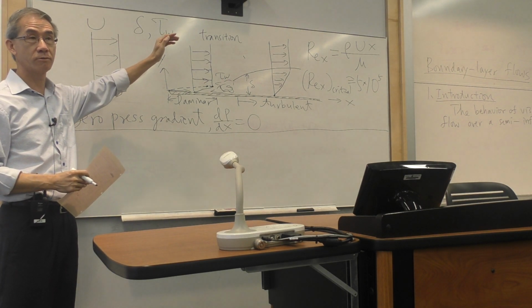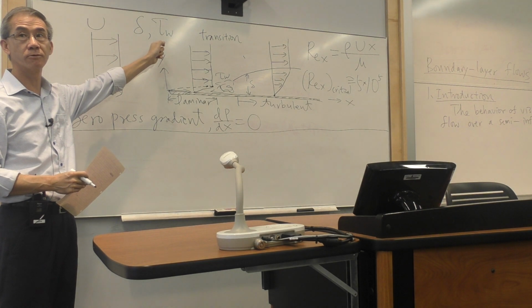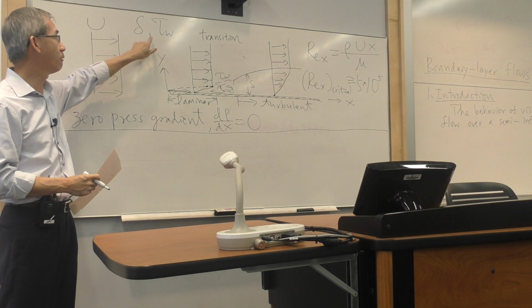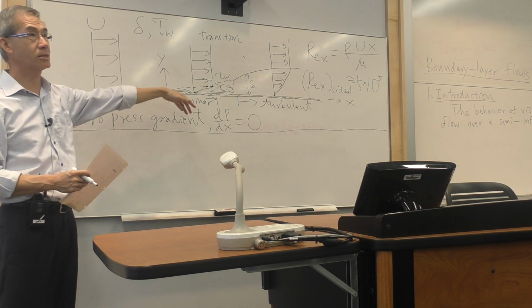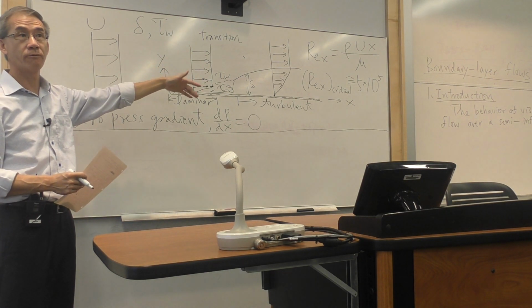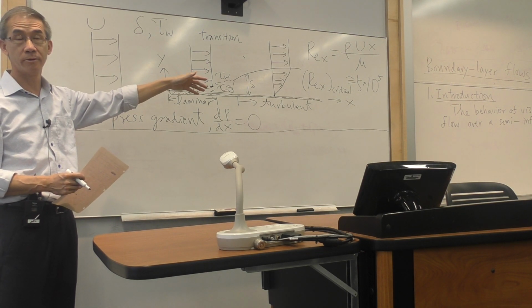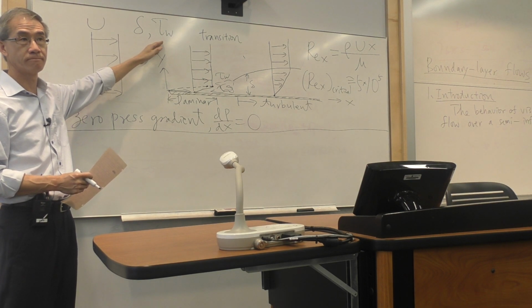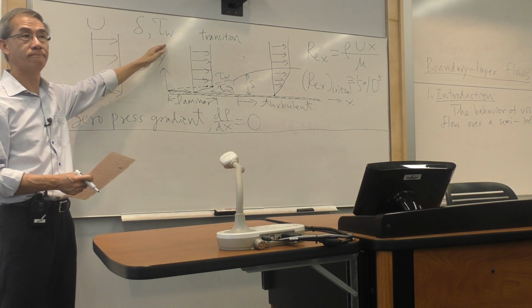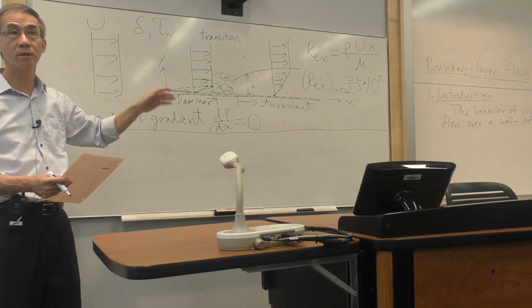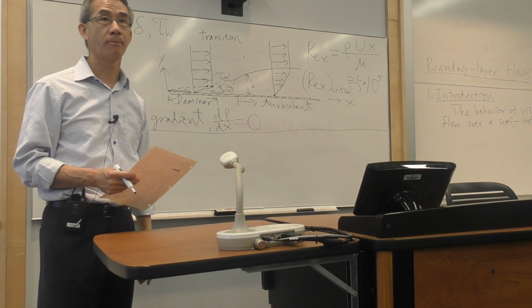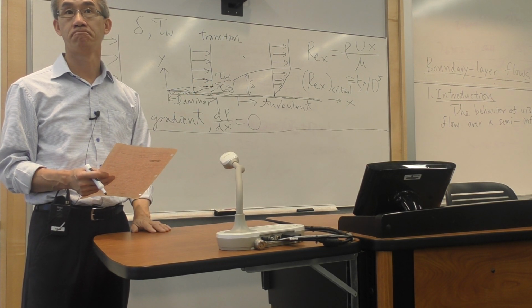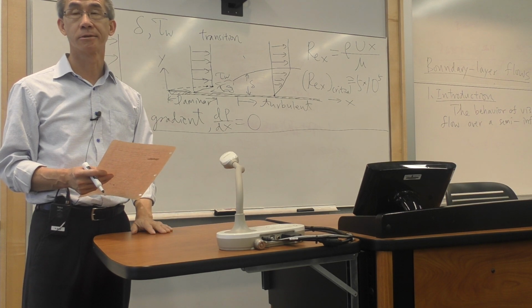And actually in 2 or 3 weeks, I'm going to derive those equations for you so that I have a tool to estimate how thick the boundary layer is at a distance of, say, a foot from the leading edge of your car hood. And I'm going to also estimate at that location what the shear is. Is it 10 pounds or is it 100 pounds? And that accumulatively will equate to the drag force that the power in your engine has to produce to keep the car running at constant speed, in addition to the friction in the tires, right?